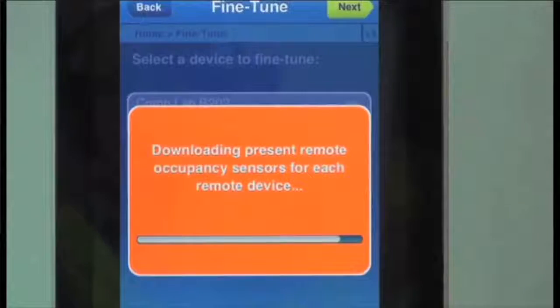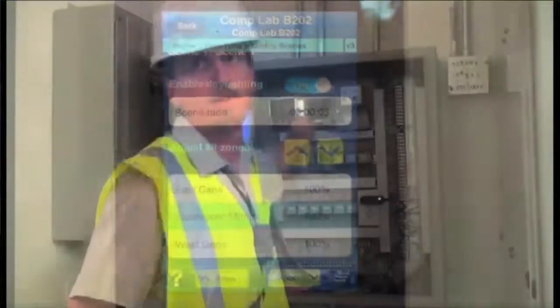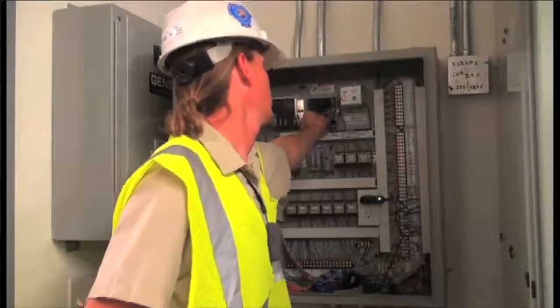We also did electrical systems, lighting control system, verifying the lighting aspects, also the power systems with your UPS, generators, switchgear, and also the monitoring of it. So all those items will be tested by the commissioning authority to ensure that they meet the basis of design and the intent. So with the commissioning agent, obviously they're the ones that are in charge of leading the